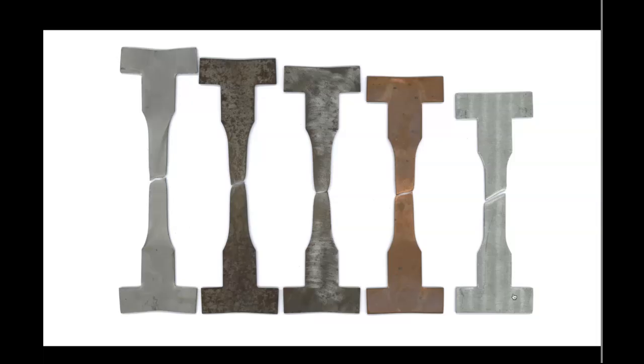They're easily bent, they're too stretchy, they're too ductile, and this is exactly what you see on the slide. The stainless steel elongated the most, and it also formed a relatively uniform stretching area. So you now can contrast it relative to plain low carbon steels.